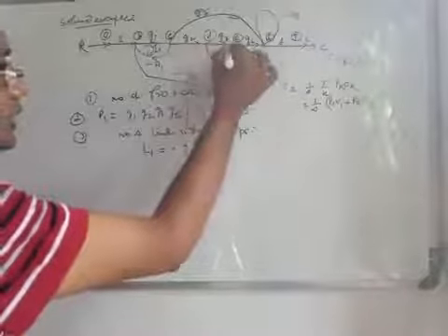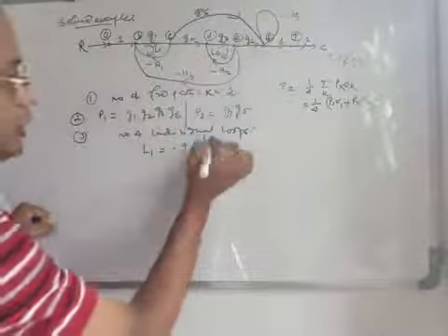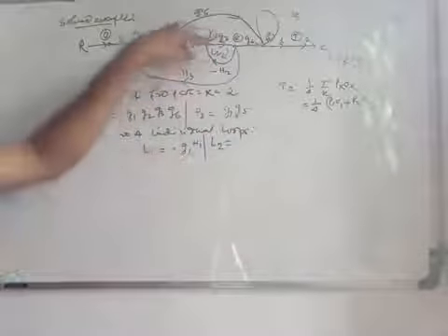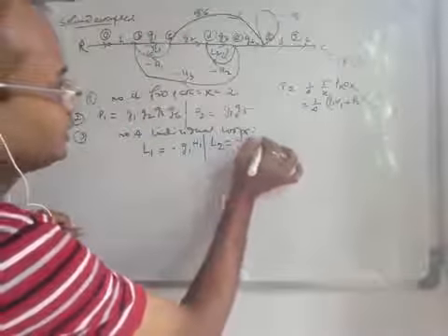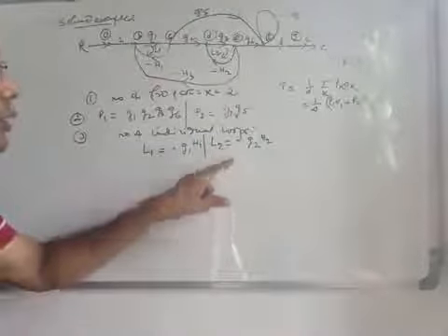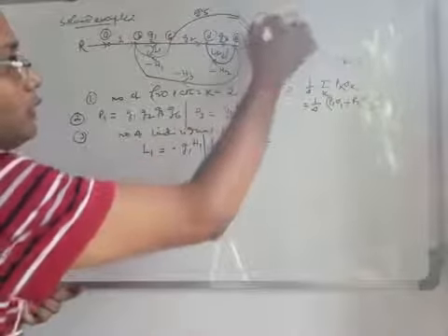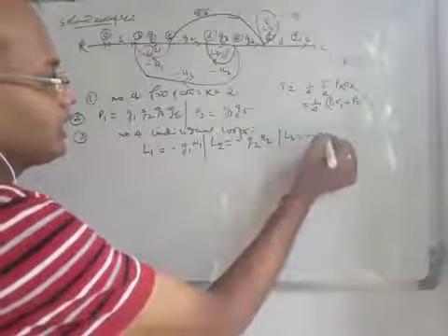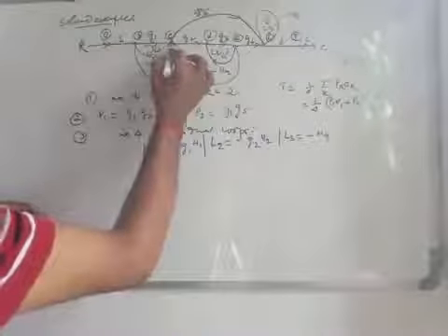Similarly, you see this is a simple loop. This is L2. So we found the second loop, with gain G2 into minus of H2, that is minus G2 H2. That is another loop with the loop gain we found. Obviously this is the same loop we already know, we might call it L3, that is minus H4. Is there any other loop?